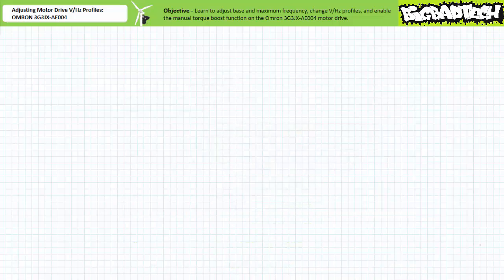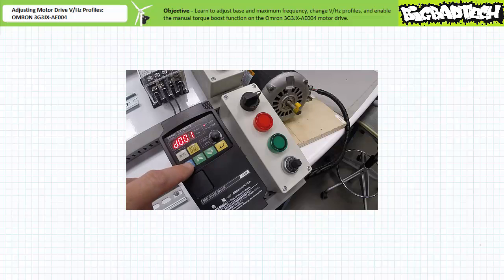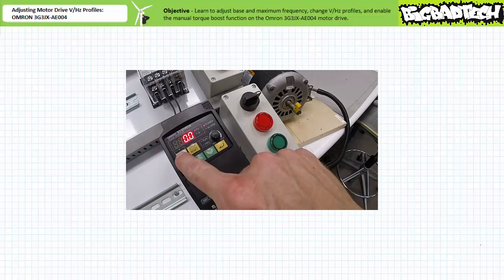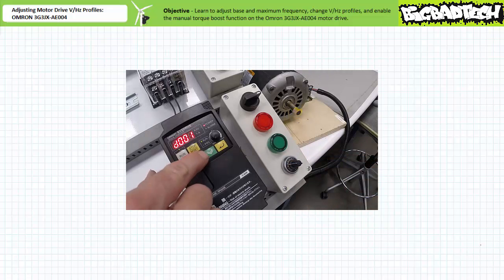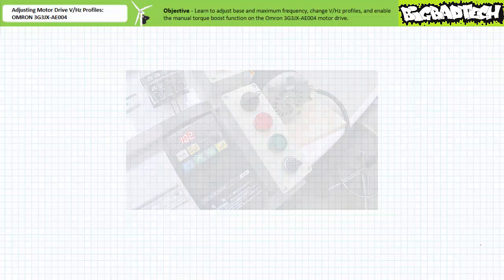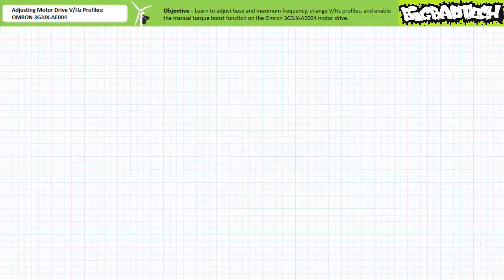When we start the motor drive with parameter D001 displayed, the output frequency monitor, we can adjust the speed potentiometer to provide an 18 Hz excitation frequency. This is our programmed manual torque boost frequency. When speed stabilizes, we can navigate to parameter D013, output voltage monitor, and find the motor drive is applying roughly 50% of the available line-to-line voltage. If this motor drive was still using the linear volts per hertz profile without the torque boost modification, we'd ordinarily expect only 30% of available line-to-line voltage, given an excitation frequency of 30% of base. I think this is a pretty cool feature, as should you.